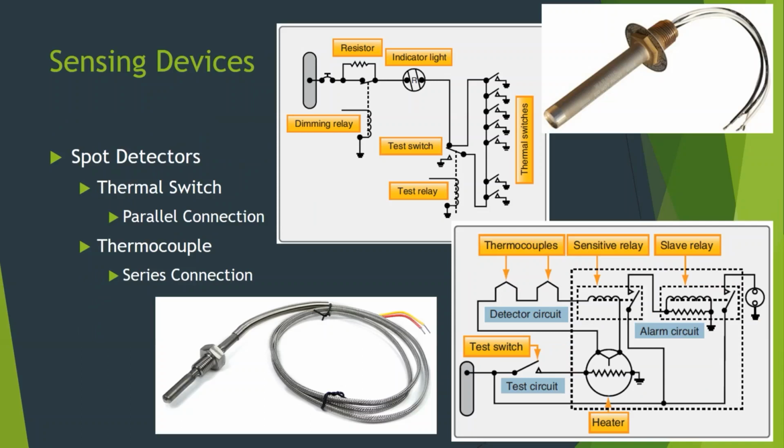And then this one, or this one, or this one, or that one over there can trigger it, okay? Whereas with thermocouples like this, if this one on the left is creating a voltage, it will pass through the thermocouple here on the right and be able to trigger that. Now, what you're seeing with a lot of these thermal switch ones nowadays is they aren't even wired in parallel. They're all wired individually back to the computer.